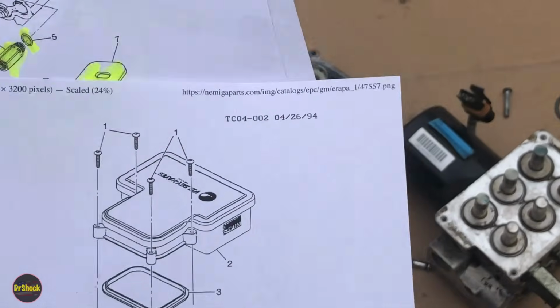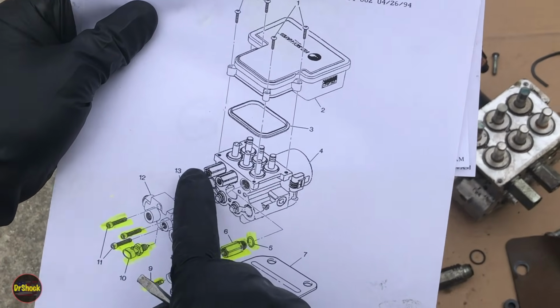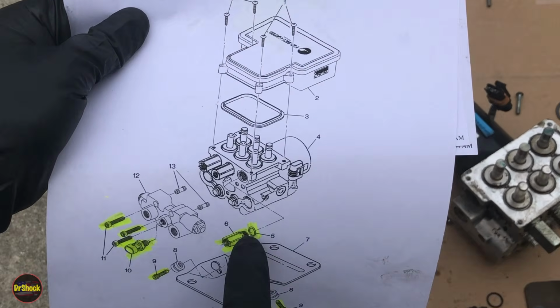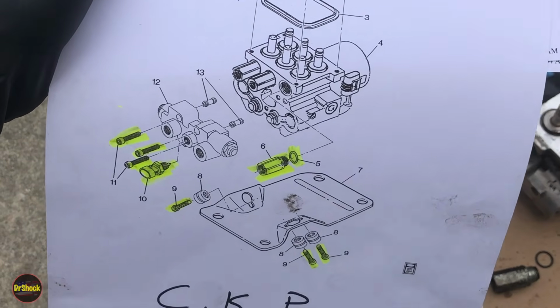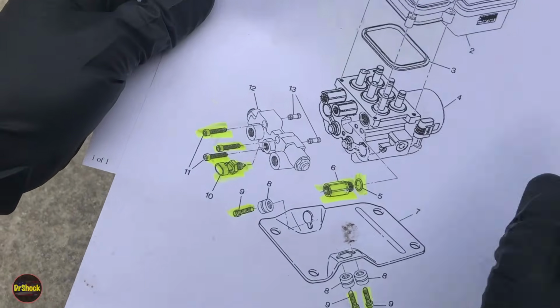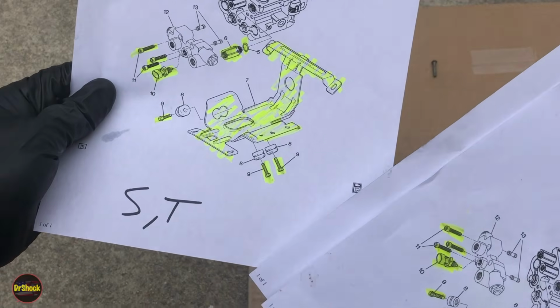They all use the same connecting tubes, these are the connecting tubes, and the same mounting tubes. So if you happen to have those and you can get a hold of one of these O-rings before they're discontinued, then you're set. They all use the same pressure switch. They all use the same hex head bolts to hold the combination valve. If you can find them, they all use the same torque to yield T25s that hold them together.